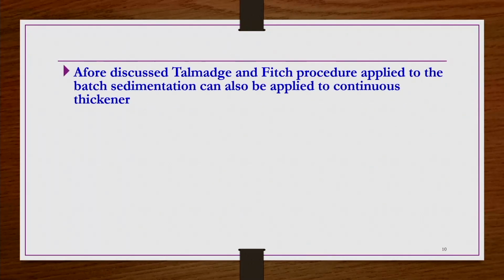Whatever process we are doing, we are doing for a batch sedimentation test. The information we are getting is from the batch sedimentation test only, but this procedure can also be applied to a continuous thickener, according to the researchers who developed this method.